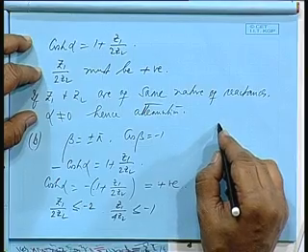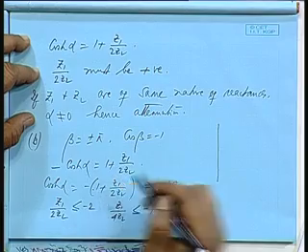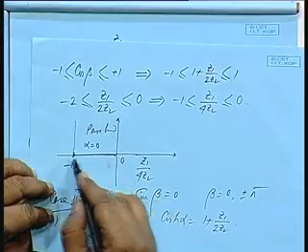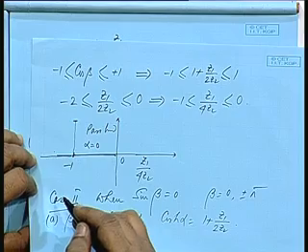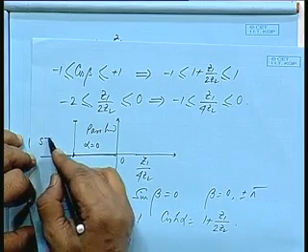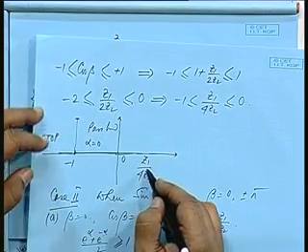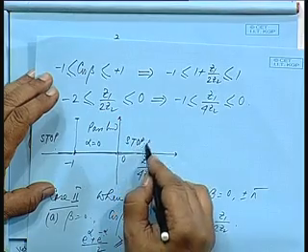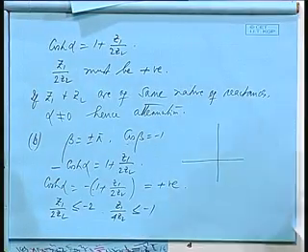So, that will be giving me alpha not equal to 0 and beta will have a value of plus minus pi. So, Z 1 by 4 Z 2 less than minus 1, this is the region where beta will be plus minus pi, and this is the stop band, this is the forbidden region. And here also, when both of them are of the same nature, the ratio is positive, this is also a stop band. Okay. So, this is what we have got now.